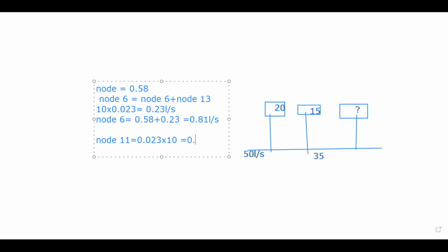Yes. 0.23. Already we know the pipe size. If I've done the pipe size for 1, I've done it for 0.58, and I got like 65 or whatever, that means this other one will be 65, unless the slope changes. But I don't think the slope will change.